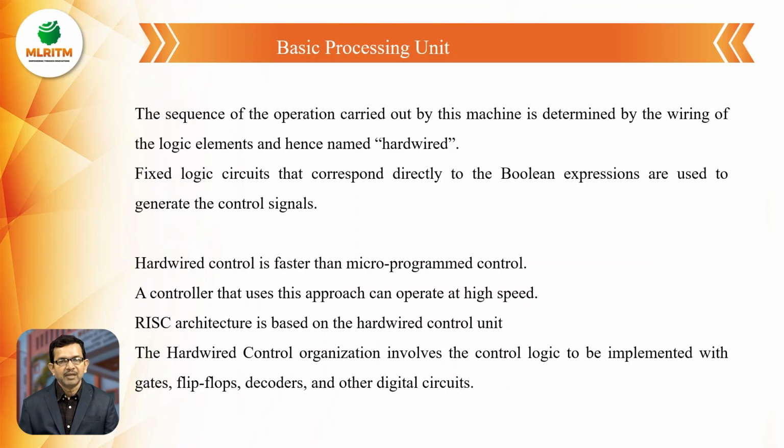If I compare the hardwired control unit with the microprogrammed control unit, both are used for executing instructions. So what is the benefit I am going to get? Is there any benefit if I use the hardwired control unit? Yes, the hardwired control unit processes the instructions very fast when compared with the microprogrammed control unit. Next, a controller that uses this approach can operate at high speed.